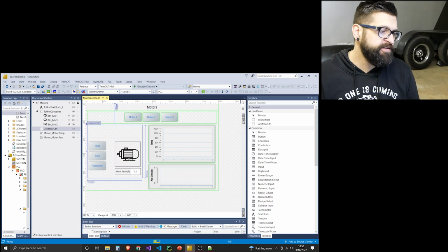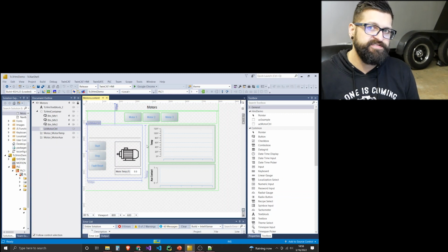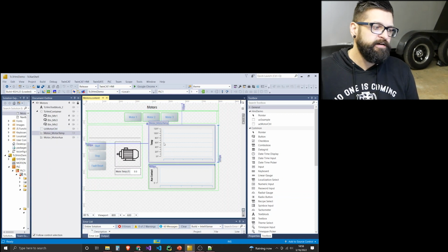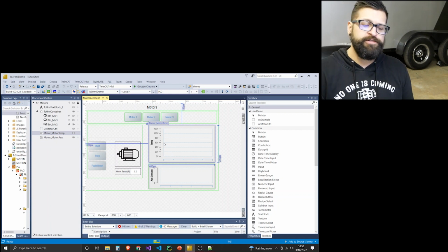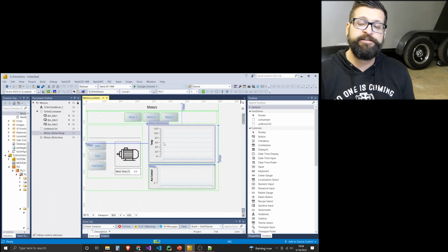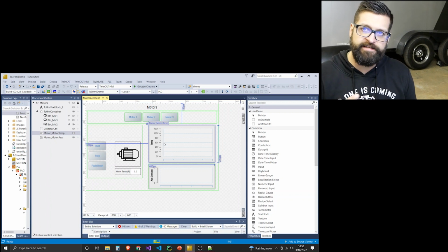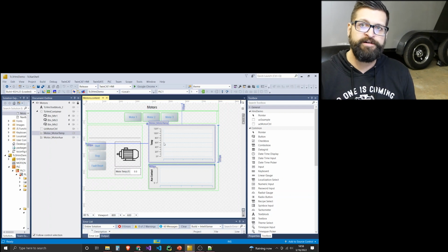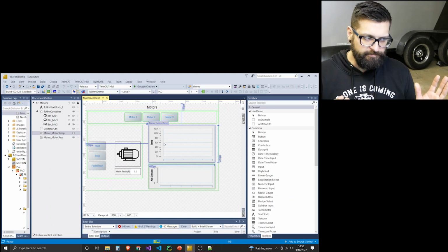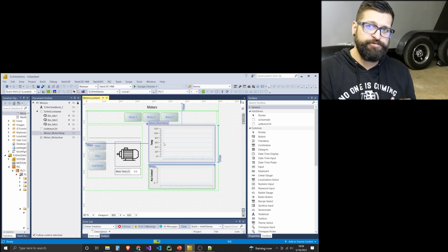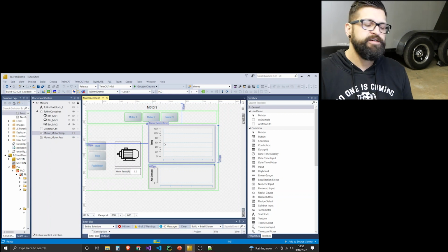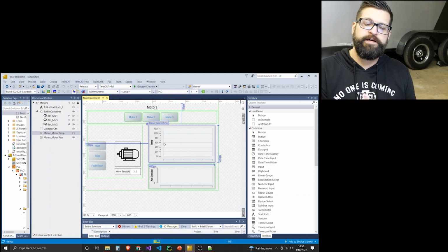Also important note, on these charts, you can have multiple symbols charting at the same time. Like one of the projects we just did, we had a really high number of heaters that we were using SSRs to control, so we could get different percentages of power sent out to resistive heating elements. Usually I have a set point that I'll trend, and then I'll have the actual temperature. So the operator can look in real time and say, okay, this is my set point. This is what I'm actually at. It's also a great way to tune PIDs.